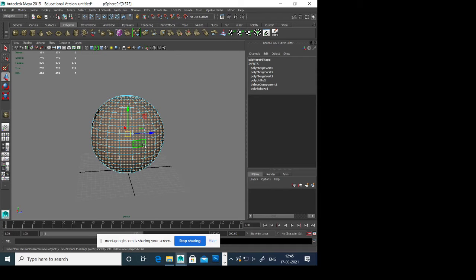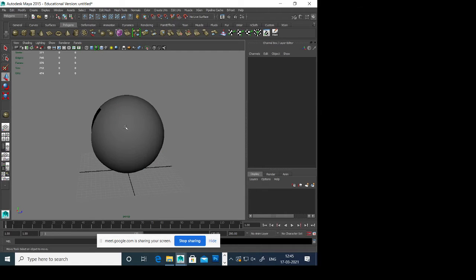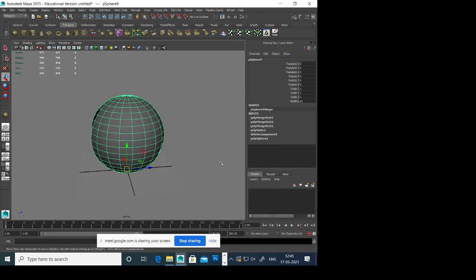And one more thing, in Max you have smoothing groups. In Maya you don't have it, it doesn't exist, and it has no use in most games. Especially if you're doing cars and mechanical stuff, and you don't have a high poly, in that case it works beautifully. But nowadays most triple A titles have a high poly. For every low poly they have a high poly model. Everything you bake from high poly to low poly is generated based on the high poly, so all coordinates, shape, volume, everything. That's why smoothing groups are not required anymore, because you are using those maps and generating everything.